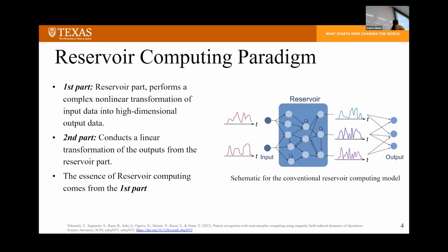What this means is that the first part creates the essence of how reservoir computing works, and makes reservoir computing a very suitable model for neuromorphic hardware-based implementations. The reason is that the learning process doesn't interfere with how the reservoir dynamics are created. Because of that, we can use any material that provides the appropriate complex dynamics and memory that we need. So the next question is how we can implement a physical system using complex nonlinearity as well as memory effects with short-term properties.